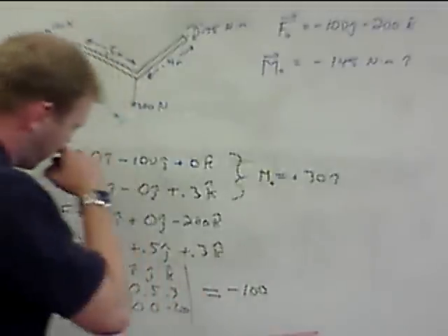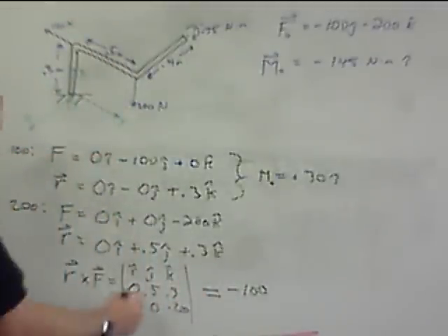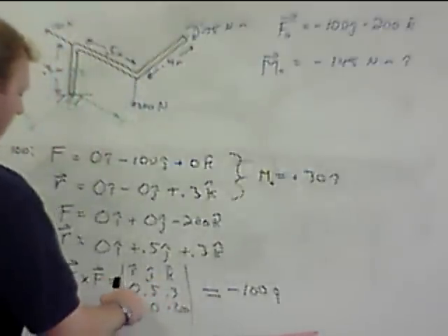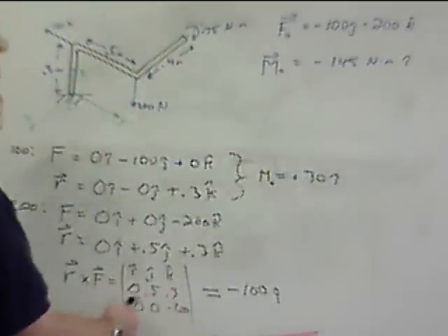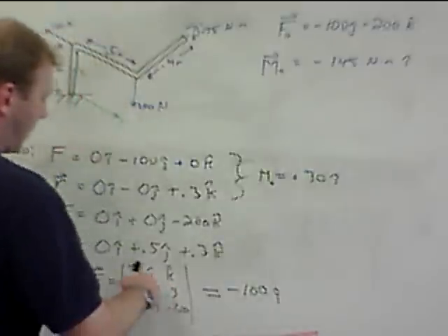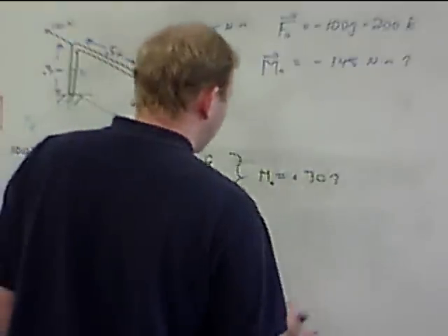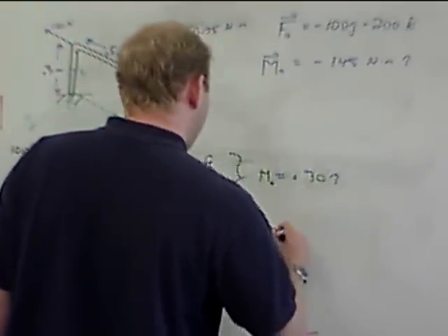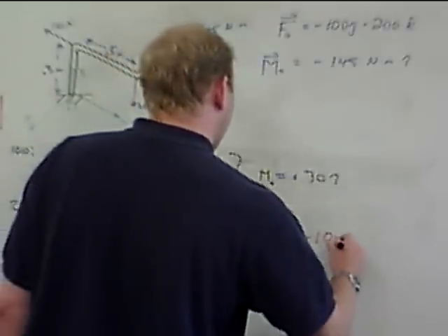So that means this is going to come out, right? Which is good. So we have minus 100I. J, we have 0 times negative 200 times 0.3 times 0 drops out. K, we're going to have 0 times 0. So we're only left with this as well. So these combine to moment about O of negative 100I.